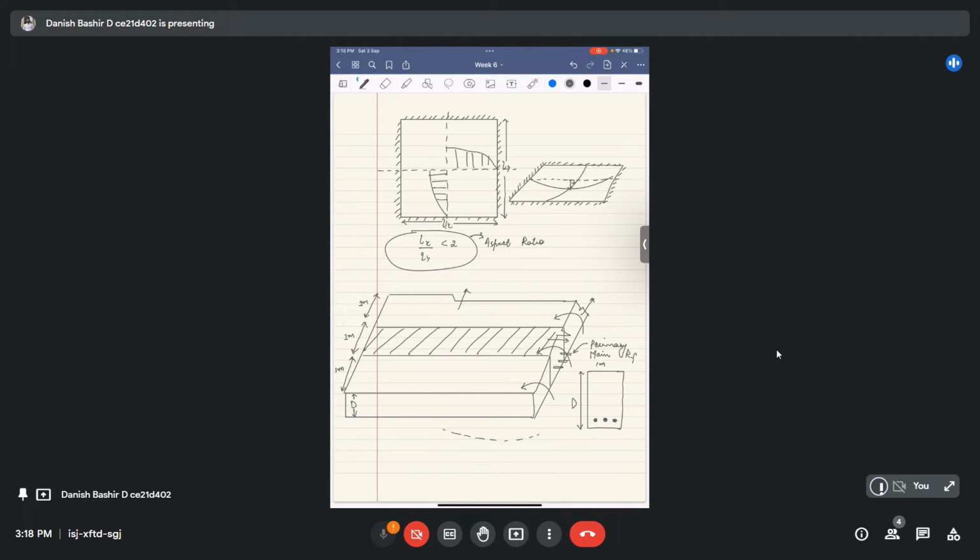It is majorly responsible for taking these transverse moments on our slab section, or the main loading that comes on it, because that loading is responsible for these moments as well. That main loading is borne by this main reinforcement. We can have this reinforcement all along our slab section like this.